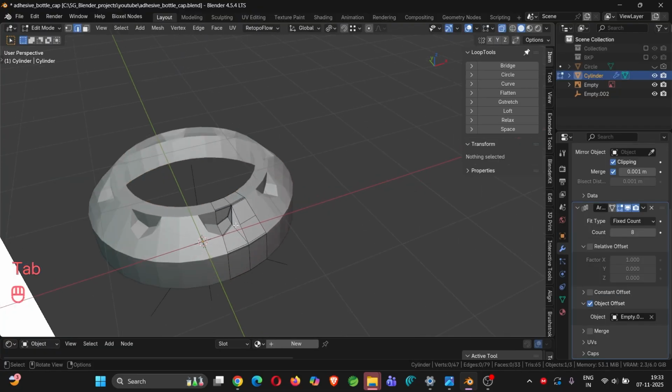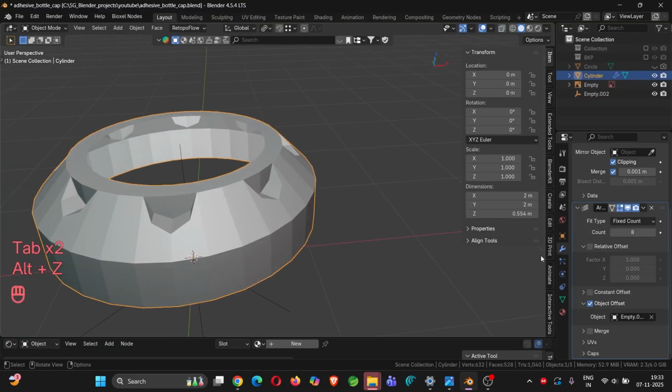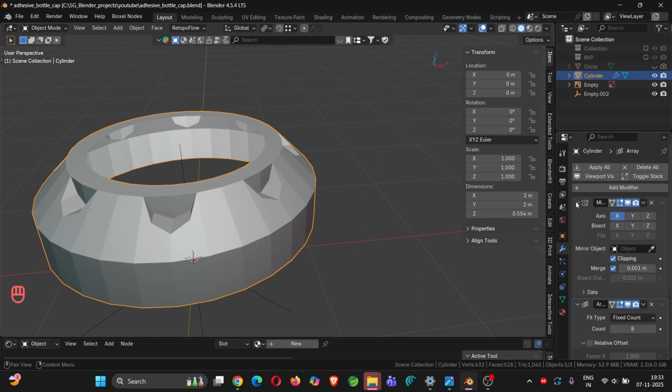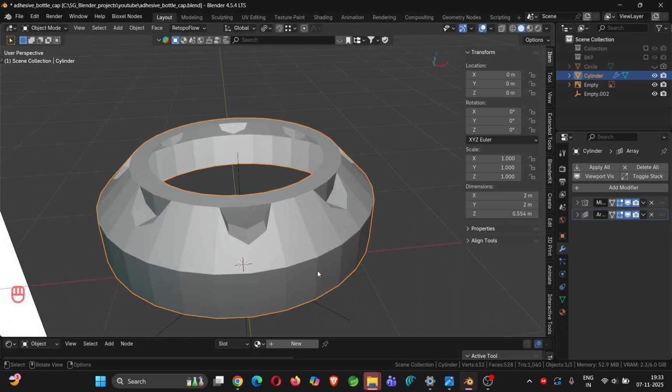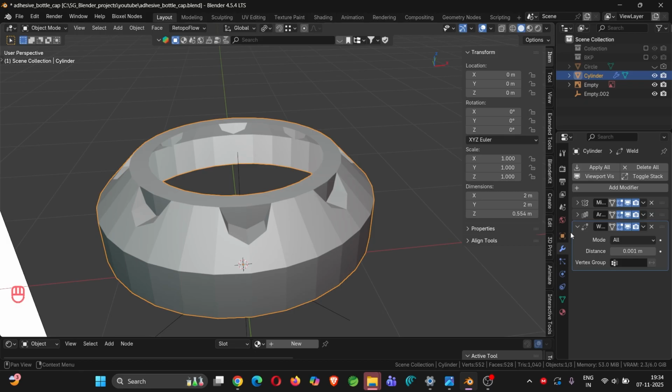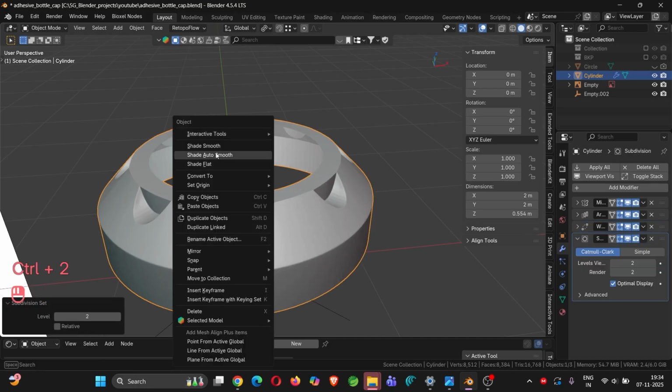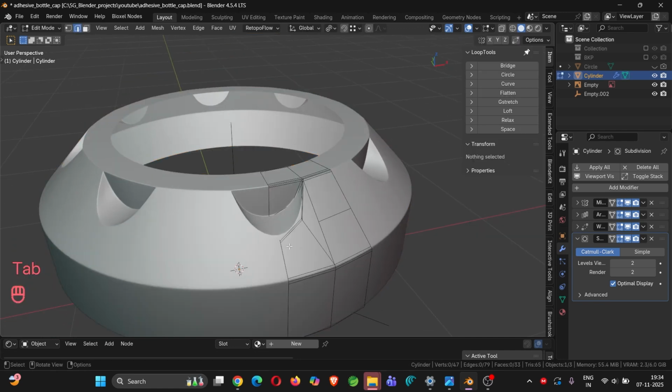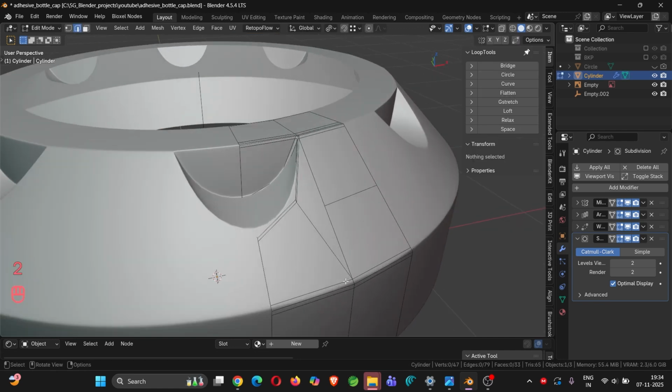Okay, so now we can see that I am getting to that shape, but our job is not yet done. Why? Because as a side product of the array going around in a roundabout, it actually merges many vertices and causes duplicate vertices. So like in the other screw modifier example I showed you, I will use the weld modifier. Before applying all the modifiers, let me also add a subdivision, and we verify how it looks now. We are happy, it looks pretty good at this point.